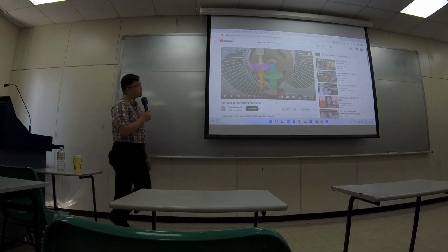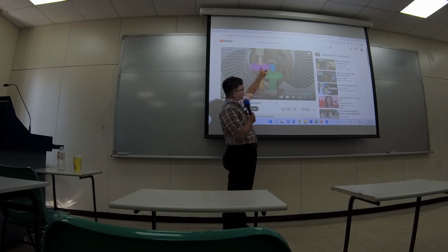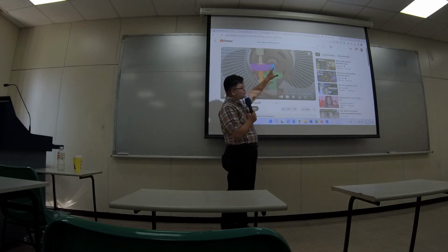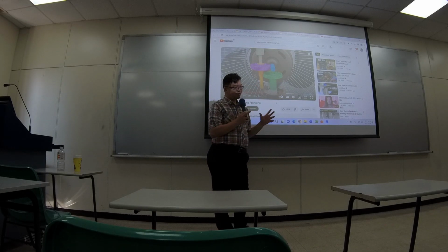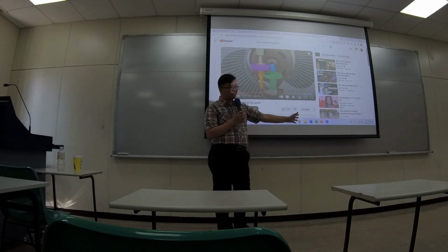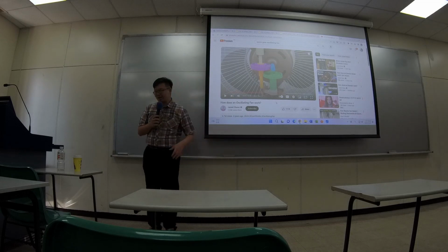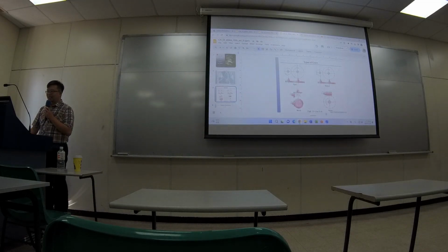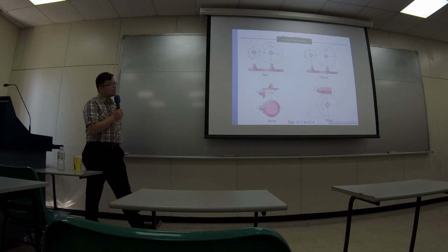Another reason why people use worm gear right here is to reduce the speed of the oscillating motion. If you directly use your motor speed applied to the 4-bar linkage, then it's gonna oscillate so fast, then it's gonna be too crazy, right? So that's the most common 4 kinds of gears.